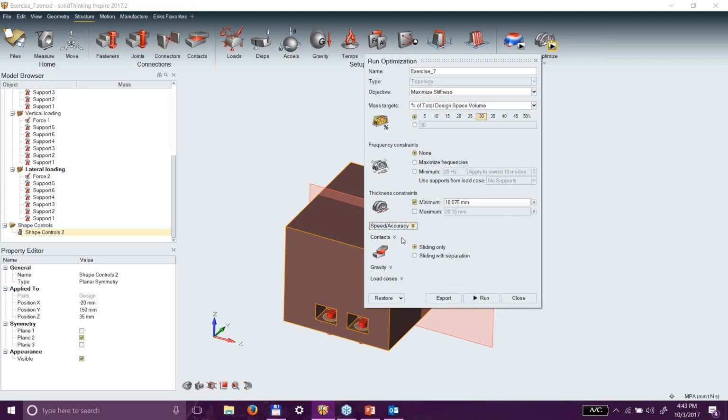Contacts. Contacts deal with the contacting surfaces. Bonded surfaces are always stuck together. But if I have contacting surfaces, I can allow them to separate. By default, think of it as two really strong magnets put together but oiled in between them. So I can slide them back and forth, but they do not want to come apart, nor will they pass through each other.